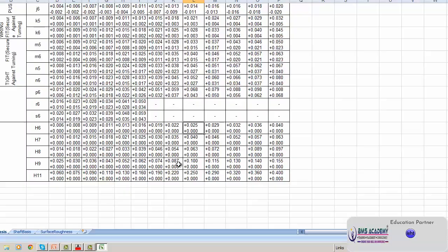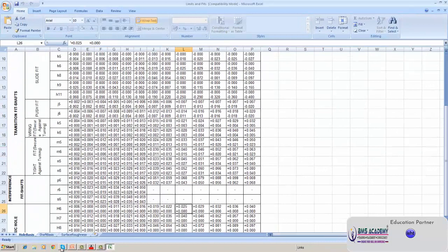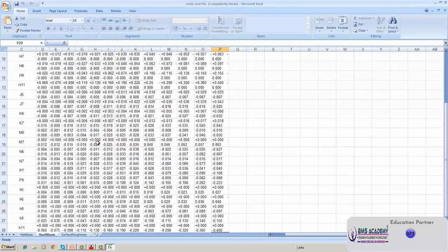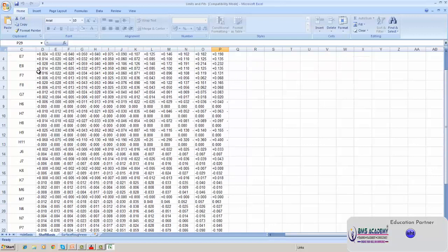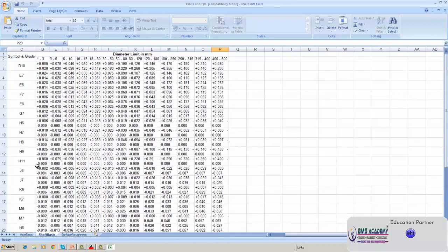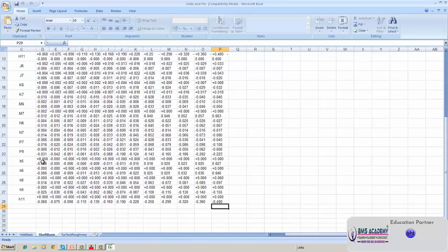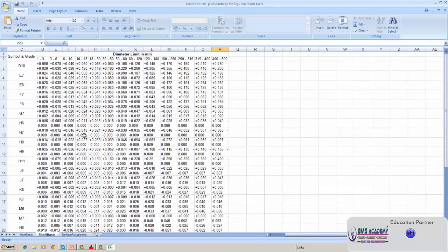So like that in many places. If minus is there, it will be a minus sign. Okay, I just briefly described the tolerance. And here on shaft basis, the shaft is fixed as a standard, and holes are fixed as variable. If shaft is variable, holes are fixed as standard. Okay, so for further details, you have to read limits and tolerances, fits, etc.